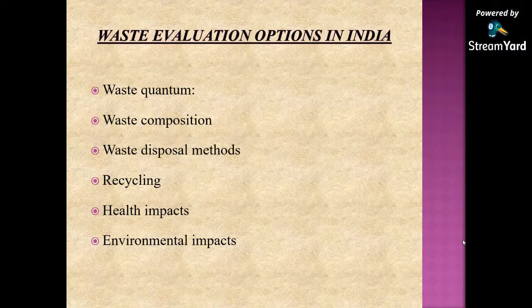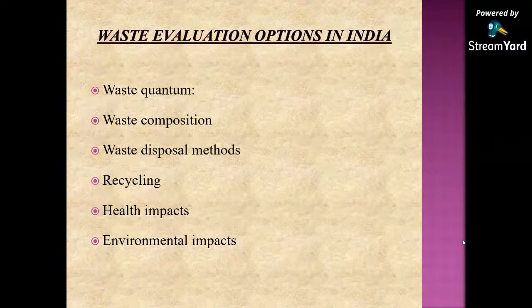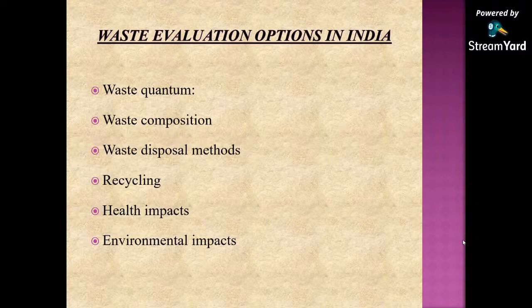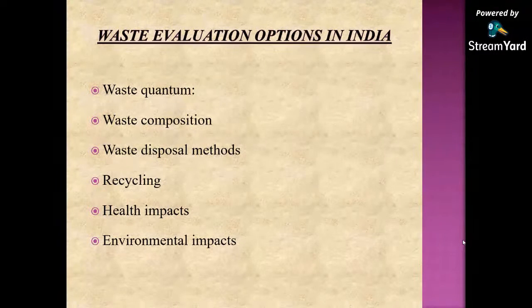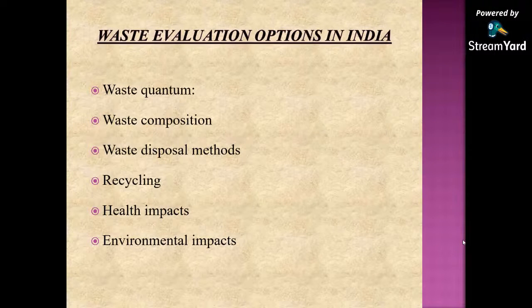The physical and chemical characteristics of Indian city refuse show that about 80% of the waste is compostable and ideal for biogas generation due to adequate nutrients. The moisture content is 50 to 55% and the carbon to nitrogen ratio is 25 to 40 to 1.